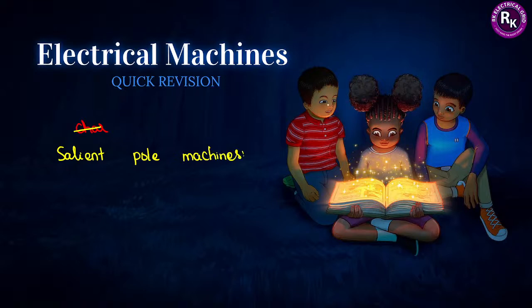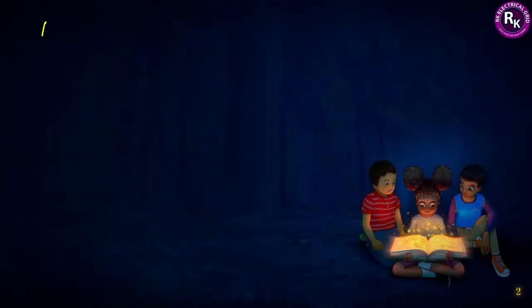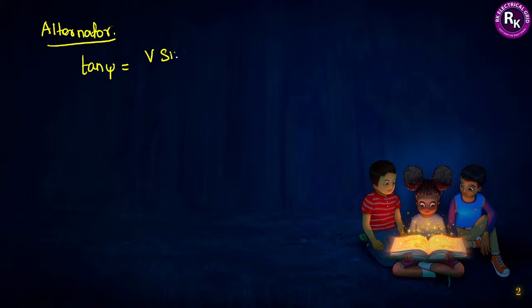In case of salient pole machine, let us break it into two parts. First one, let us take alternator. When we are looking into alternator, what you have to remember is the calculation of power factor angle: tan psi equals V sin phi plus or minus armature current IA into quadrature reactance XQ, divided by V cos phi plus IA into RA.